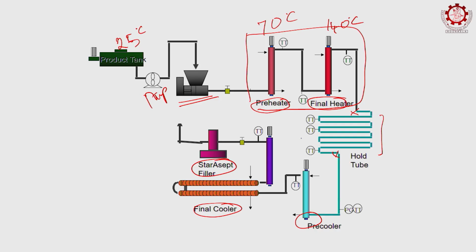The positive displacement pump, something like here, is going to be much more expensive, but it is going to have precise flow control. So, if I set my flow rate as 3 gallons per minute, it is going to deliver consistently 3 gallons per minute. Why are we using a positive displacement pump? Because of this holding tube. In the holding tube, you want your particles to spend the same amount of time. In other words, if my target residence time is 30 seconds, we expect all the particles, all the fluid in the system, to go through that 30 seconds of processing time.